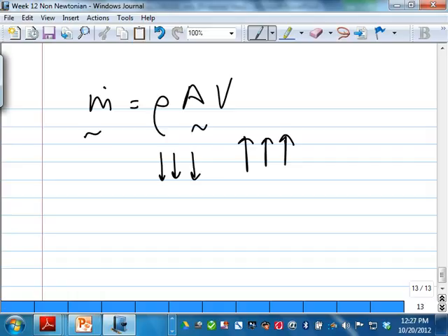So in that case, there is an acceleration of the fluid with distance. At each location, in steady state, the velocity is fixed. But from this location to a location downstream, the velocity will increase in the case of boiling. Is that okay? So with multi-phase flow, in this changing phase, you can expect an acceleration or deceleration.